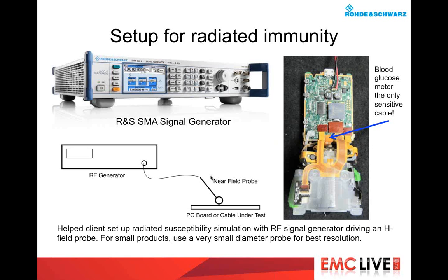Another interesting way of creating a radiated immunity check is by constructing a chattering relay, and these are kind of cool. But they produce a very broadband RF signal, which can check many frequencies simultaneously. So it's a very quick check on your circuit by holding this near. And all you do, of course, is wire the normally closed relay contact through the coil. When you plug that into the AC or DC supply, you'll discover why it's called a chattering relay.